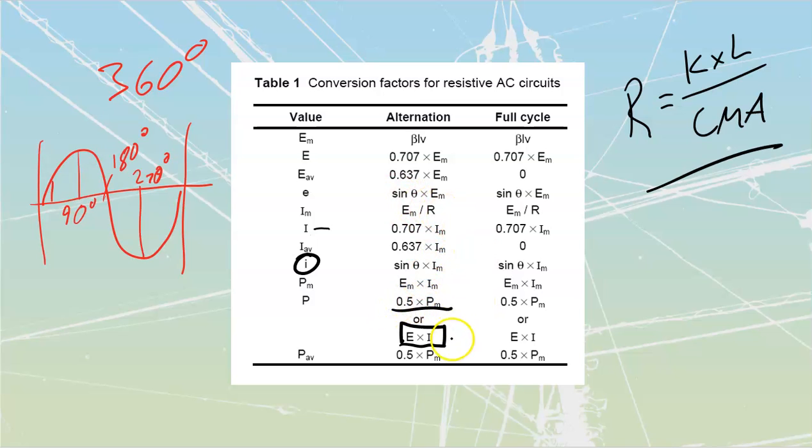It works out mathematically if you go back through it, but we're not here for mathematical proofs. We're here for electrical concepts. So work with this formula most of the time. My true power, measured in watts, is going to be my volts times my amps, all in RMS types. Average power is going to be the same as my RMS type of power, which leads to a really interesting thing. Because if my average power and my true power are equal to the exact same thing, what is the point of my average voltage and my RMS value voltage?